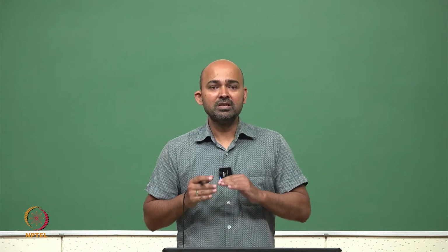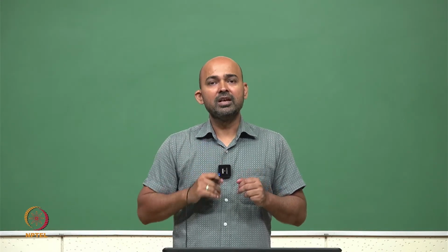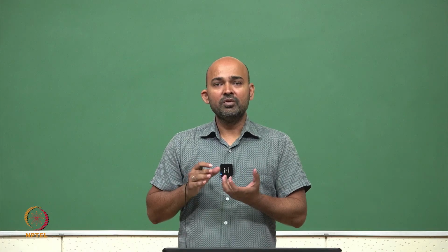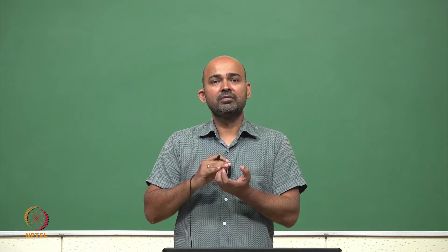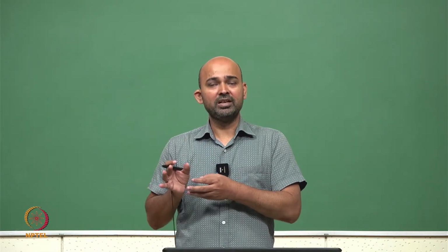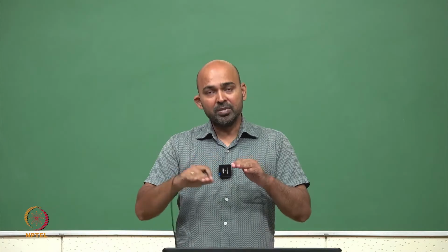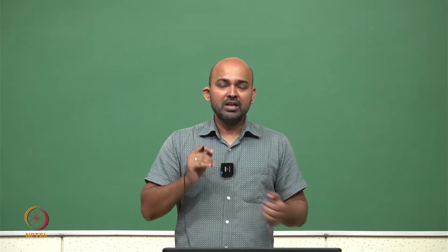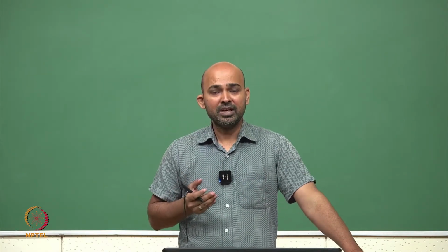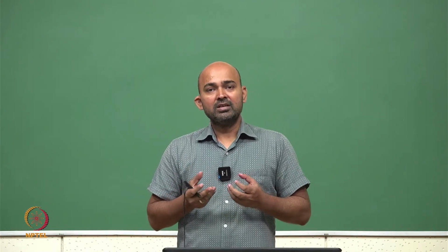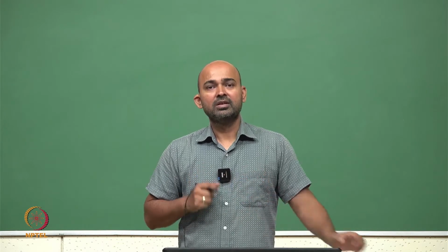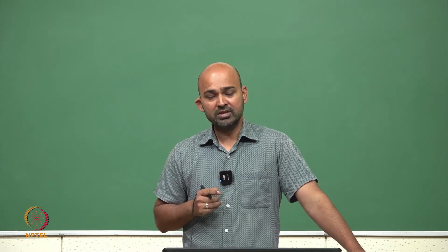Single layer PCB means all the traces, whatever connections we need to make, are all available on the front layer itself. So, the processing of this PCB, the fabrication steps required, are much less compared to the complicated PCBs where we have multiple layers to fabricate. So, single layer PCBs are very easy to fabricate, and the cost is also less. However, the circuit complexity also should be less to provide only on a single layer.